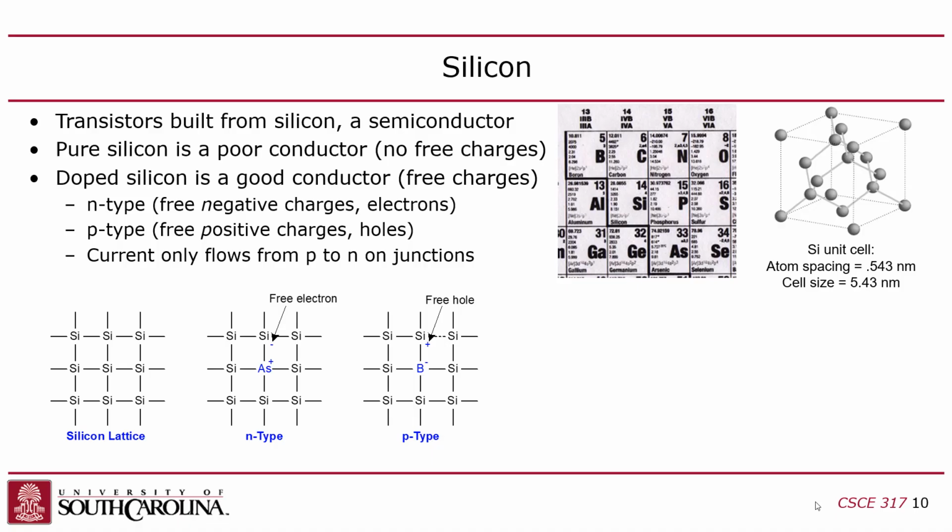And so what happens in that pure silicon crystal lattice is each silicon atom forms covalent bonds with 4 neighboring atoms. Okay, and it creates this really neat repeating structure. If you look at the bond angles, basically the angle of each silicon atom relative to the others, those angles are repeated, and the smallest unit of repetition is called the unit cell.